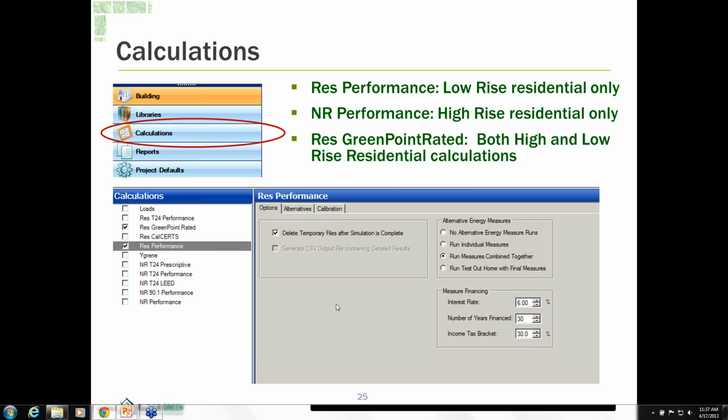In actual, I haven't really had the need to use interior partitions when I'm doing any energy compliance for Title 24, and I haven't had any plan checkers ask me to include that into the model simulation. So they only wanted to see exterior walls, not partitions.